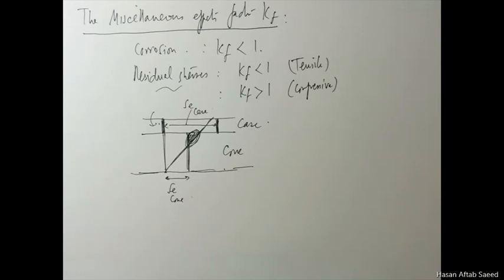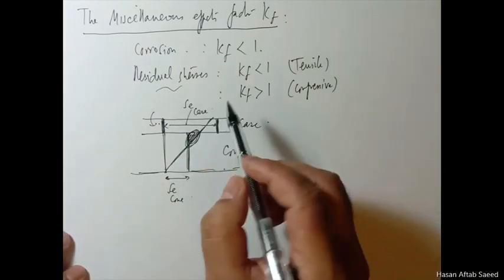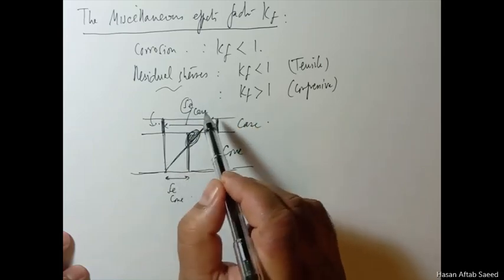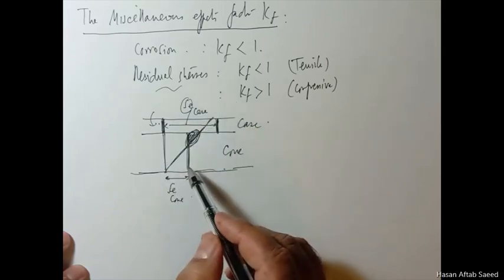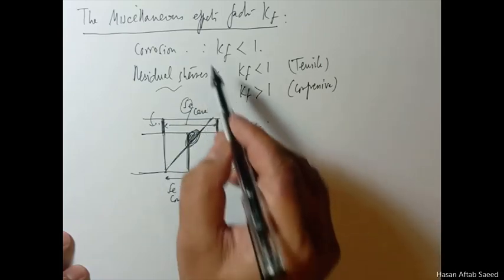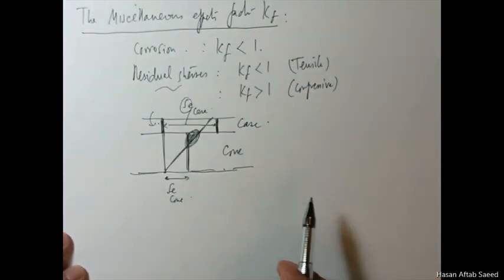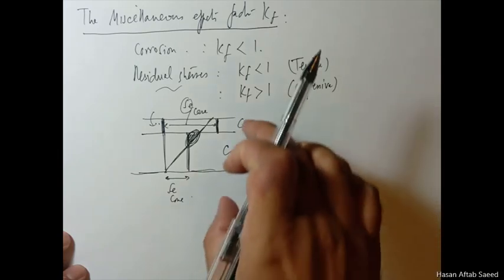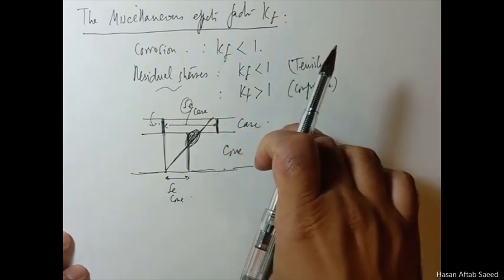So these are the things. If such a situation is there, first of all we need to make sure that we don't use the SE of this case here. We need to consider using some sort of a correction factor for this situation, so that we are not misled into believing that this part will have an infinite life.